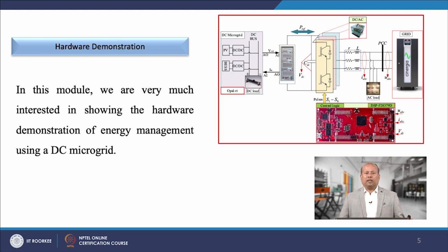The same current signal is either fed or drawn through a current source at the DC bus of the DC microgrid inside the RT-LAB of the Opal RT. This looping system between Opal RT and the power amplifier effectively emulates the DC bus of the DC microgrid.